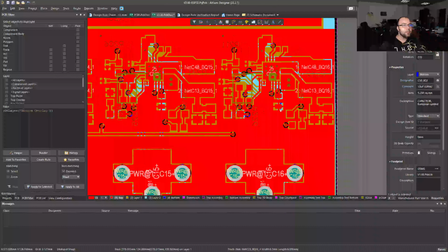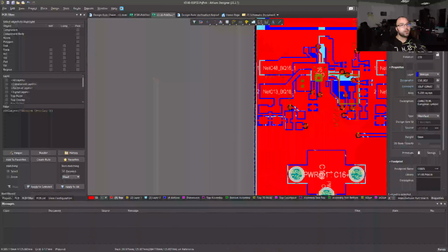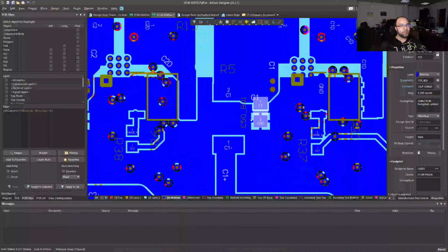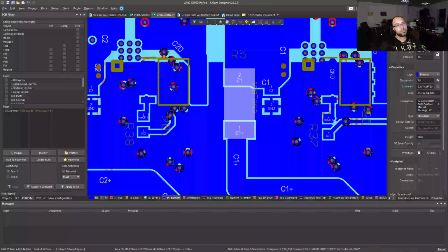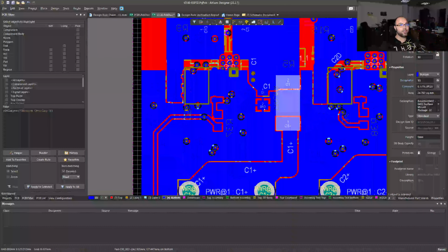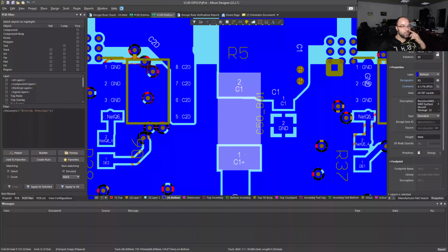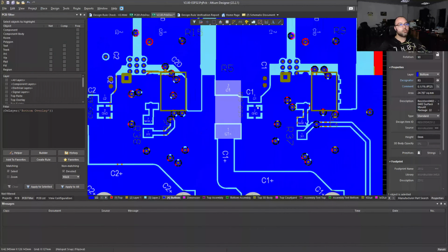It should be on the back, but it's strange sometimes when you flip the board. Now here is the shunt, here is just a cap. When you flip the board, sometimes you lose the place where you are at. So yeah, this one is the shunt that's measuring the current drop, and this one is a capacitor that's 10 microfarads.